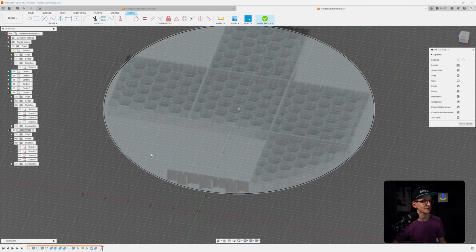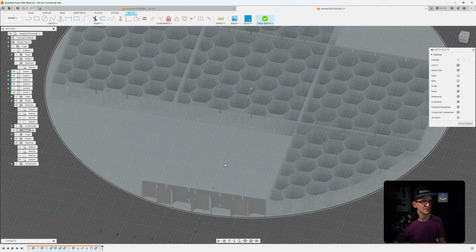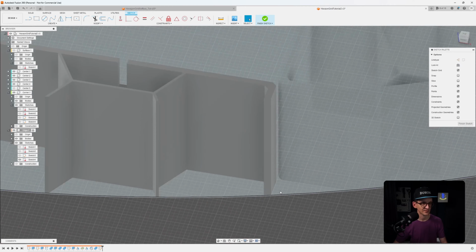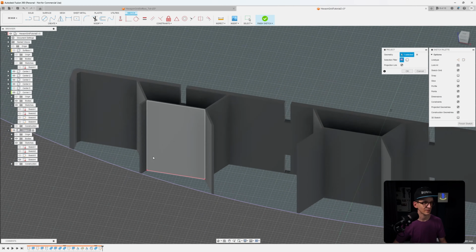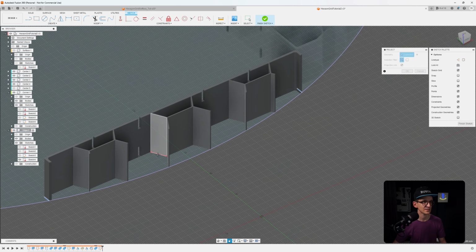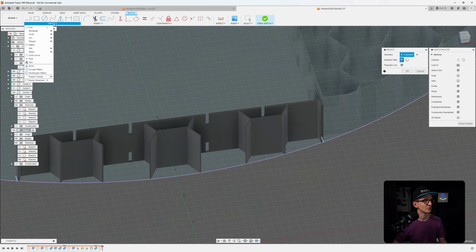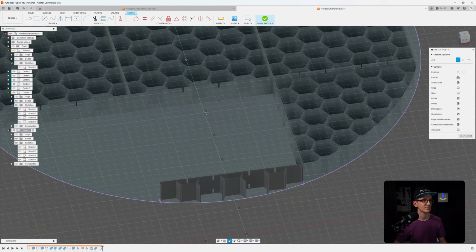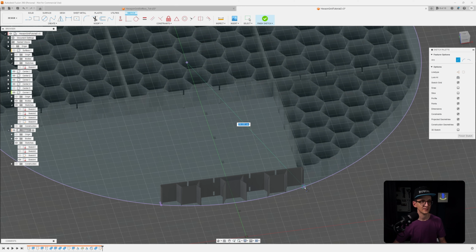Now we don't need the soft anymore. And we do the same as before. No, we need to reference again the outside edges of our corner piece. No, the edge piece, as I call it. And then we go to create an arc and center point arc. We go to the center point and span the arc like so.